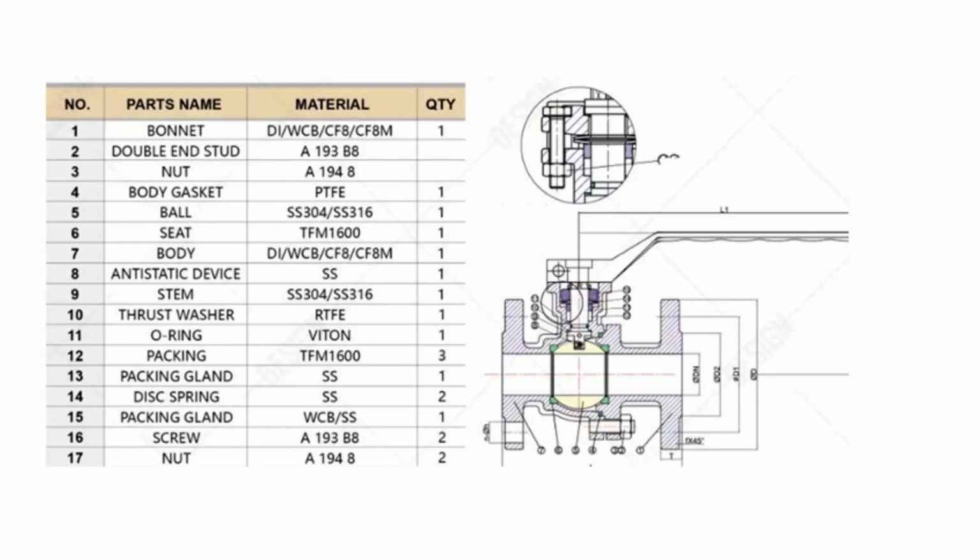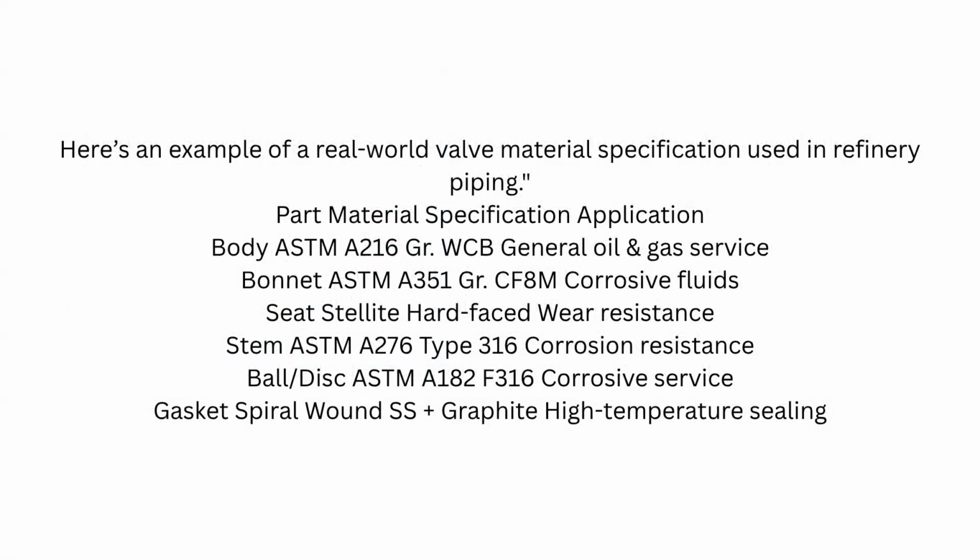Anti-static device: stainless steel. Thrust washer: RTFE. O-ring: Viton. Packing: TFM 600. Packing gland: stainless steel. Disc spring: stainless steel. Screw: A193 B8. Nut: A194 B8.